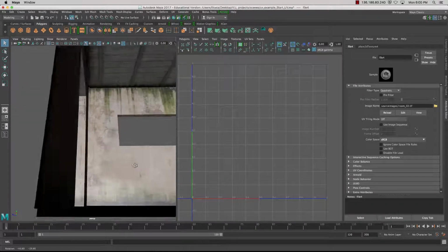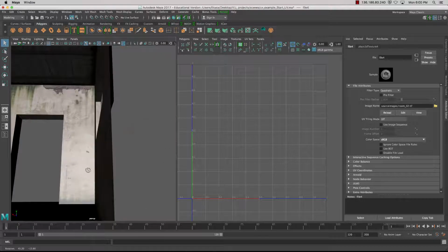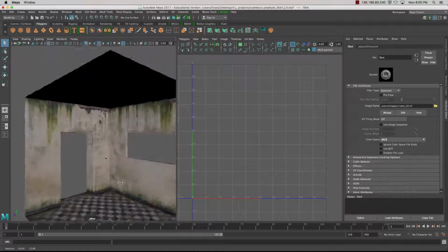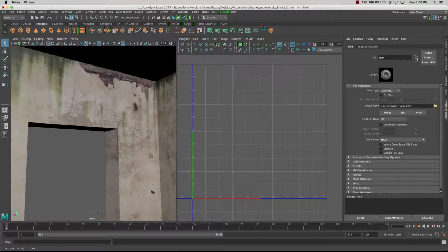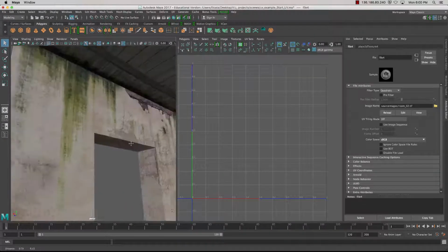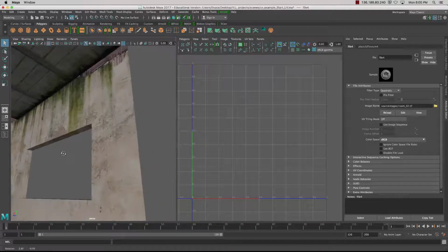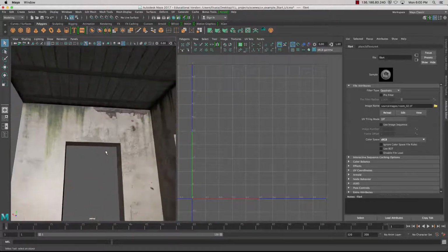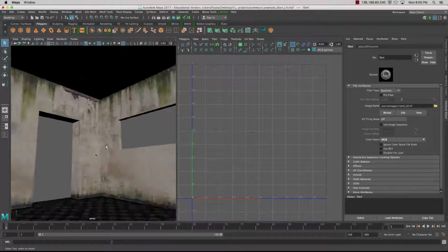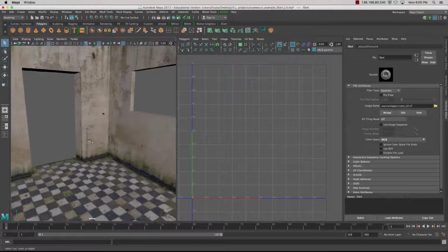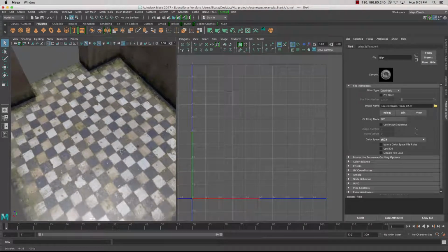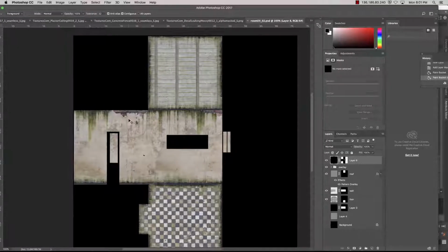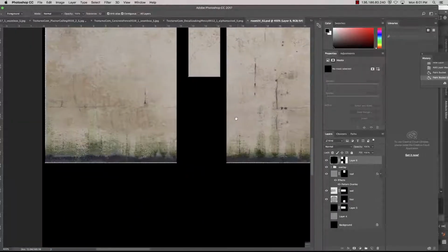So at the moment, we've just got specular turned on for everything. So everything looks super shiny. There's no change in the specular color in different areas, where in reality, the specular would be on smooth areas and also wet areas. So very shiny areas will have high specular, where dull areas will have no specular. So let's look at creating a specular map. And what I'm going to do is utilize Photoshop to do that. And then I'll also show you a method where we can do it straight inside the hypershade. And yeah, I can even see that image issue down the bottom here.